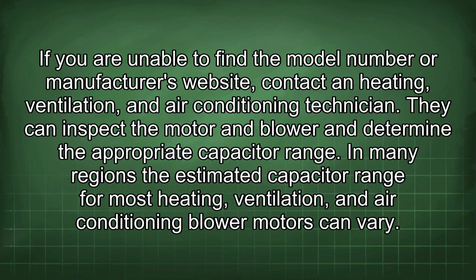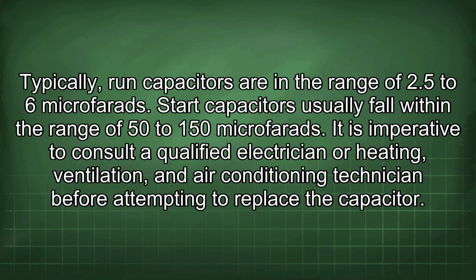In many regions, the estimated capacitor range for most HVAC blower motors can vary. Typically, run capacitors are in the range of 2.5 to 6 microfarads. Start capacitors usually fall within the range of 50 to 150 microfarads.